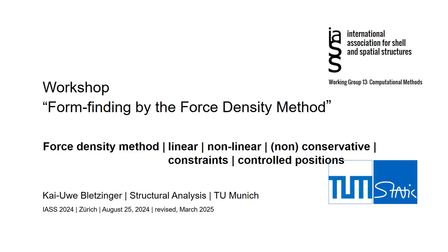Now we are ready to look at the force density method, nicely prepared with the previous seminars. In particular, we would like to spend time on all important issues and aspects of the method, such as the linear force density method, the nonlinear one, treating non-conservative issues together with self-weight and snow load, treating constraints to predict the source of nonlinearity, and alternative parametrization to deal with controlled node positions.